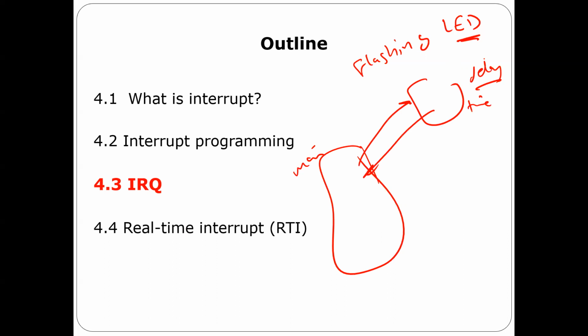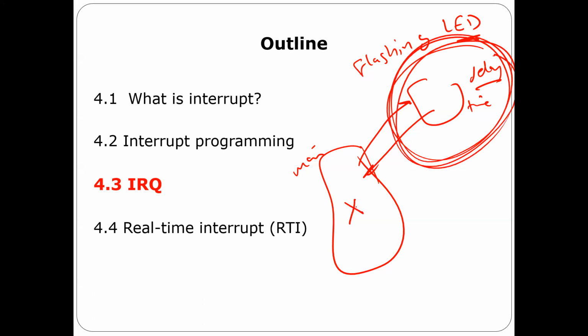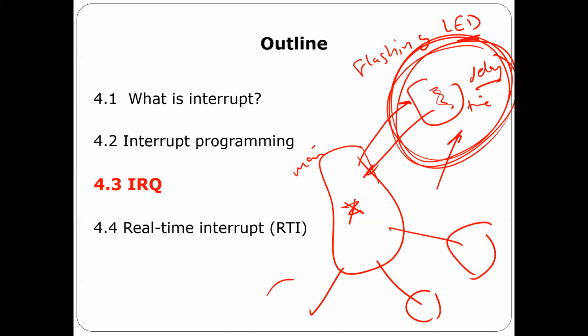When I execute a subroutine, I suspend the current task, and I'm also not going to respond to other interrupts. Maybe not in this course, but in real applications you have to be careful. You should not spend much time in any subroutine, because it is going to impact the other tasks.